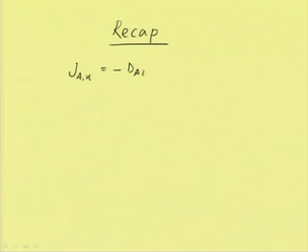In the previous lecture, we have discussed Fick's first law of diffusion, where for one dimensional diffusion in a particular direction x, we can write the molar flux J_Ax = -D_AB dC_A/dx. dC_A is the concentration gradient and dx is the distance, and D_AB is the diffusion coefficient. The negative sign indicates the drop in concentration towards the direction of diffusion.